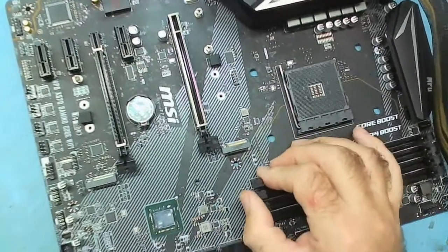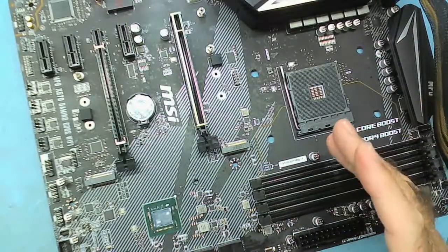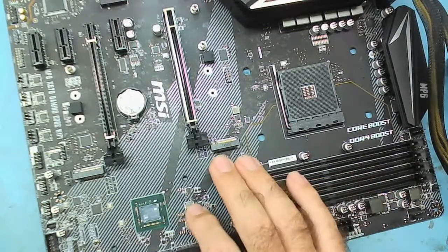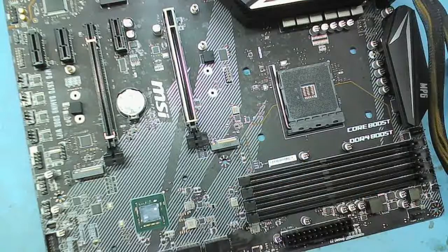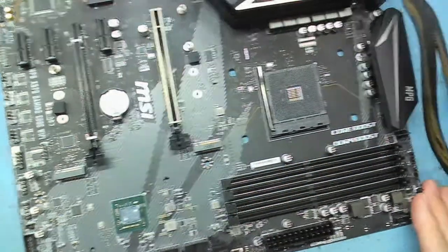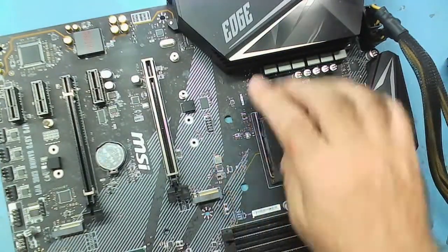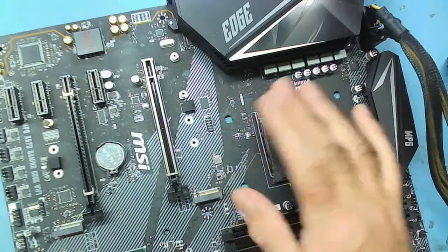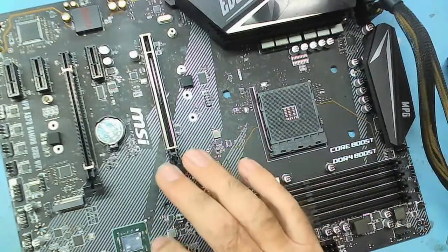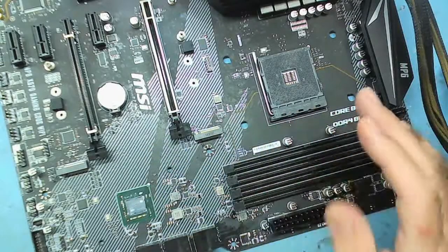I'm labouring the fact, aren't I? I'll tell you where it comes from. It comes from voltage regulators on here. So that 5 volt standby is running some voltage regulators, and I can see there's one here, there's one here, there's one here, there's one here. That might be one, but I don't see a coil there. But there's a group of voltage regulators down here. There's some more here, but they're probably for the RAM, and there's one over here, and these are your VRMs, they're for your V-core. But I suspect that one of these here, or 2 of these, are powering that.